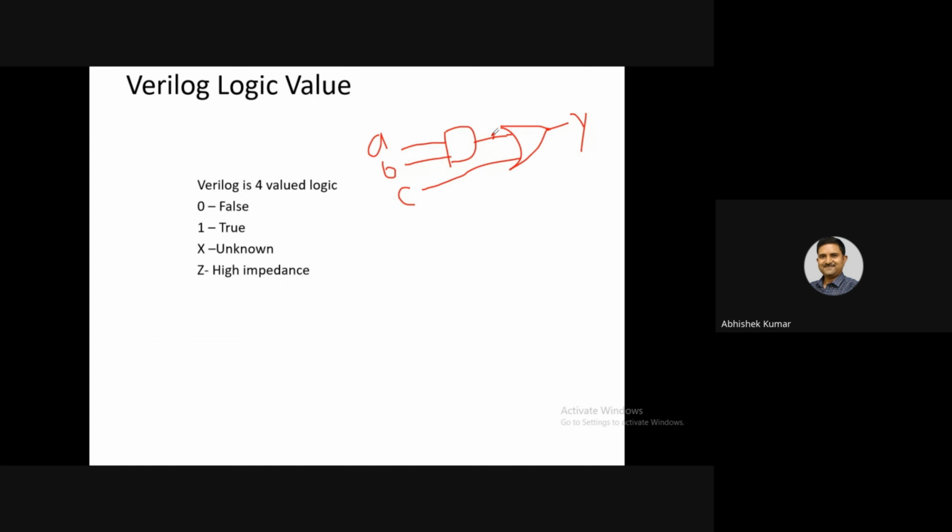Okay. So now, in Verilog, it is necessary that for every logic gate, here we have two logic gates, AND and OR, I can define the name of this logic gate as A1 and the name of this one as O1. So we have to define some local name for every logic gate.